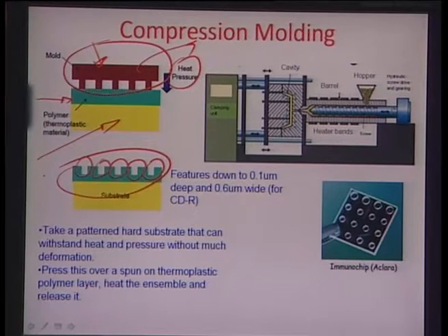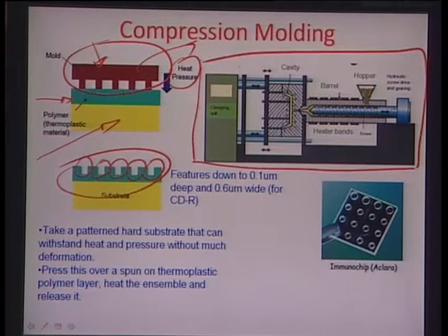So, the very common compact disc that we use regularly in our computers or audio equipment is essentially realized using the compression molding process. And another very important technique which is often used is injection molding, which is illustrated here in this particular figure. If you see this illustration here, there are two dies which are mating components, and there is a small gap in this region between the dies, which is the shape or the feature which has to be replicated.